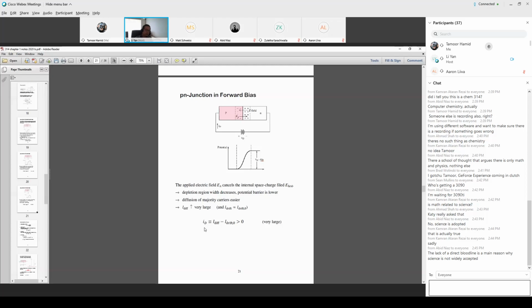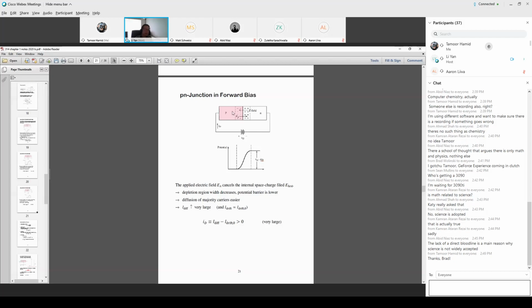So finally, you also have an imbalance of the overall current. Diffusion current much outweighs the drift current. So you have a plus sign. Plus sign means the diode current, as indicated in this direction, is indeed going this way, consistent with the polarity of your power supply voltage.